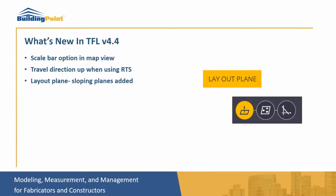Layout plane, like I said, was enhanced here, and they brought in sloping planes. Under the layout plane, two new icons were made available. The first one was just for horizontal planes in the previous version, and then they brought in the capability of creating a slope plane by selecting 3 points. So if you have 3 points in your job that have different elevations, the software will compute an inclined plane or a sloping plane out of these 3 points. And the plane will not only be within the 3 points that you've selected, but will extend to the entire job site on which you're working. So this is the middle option.